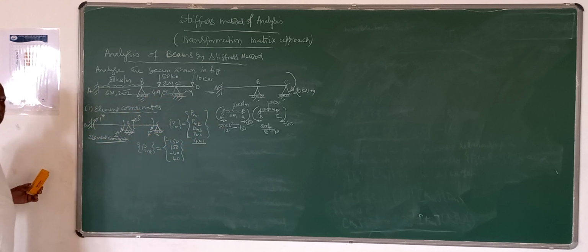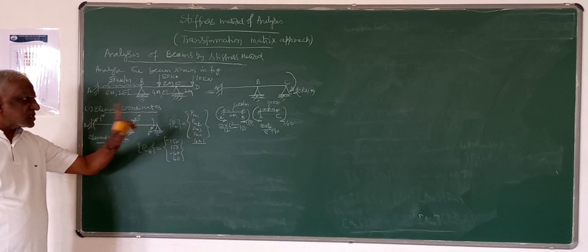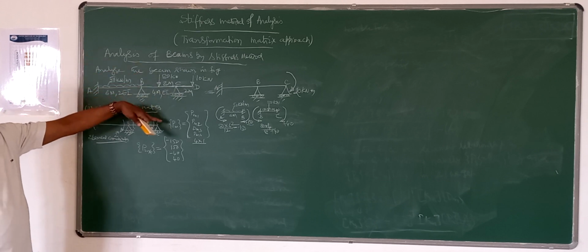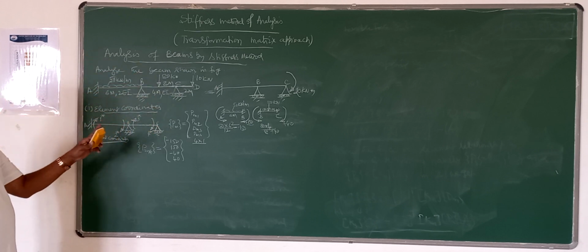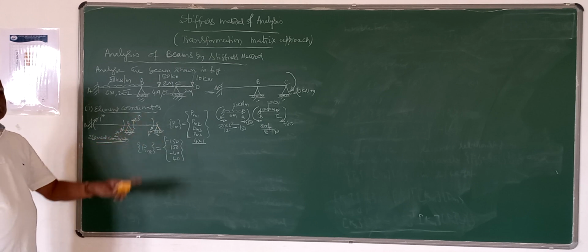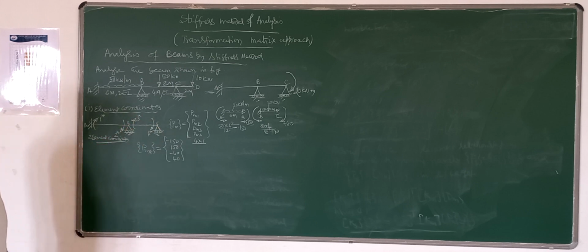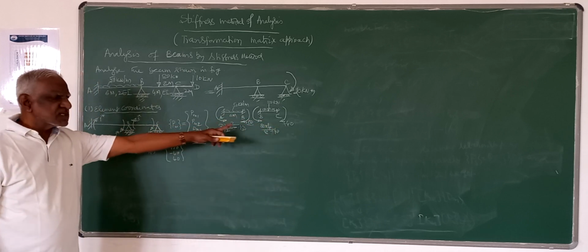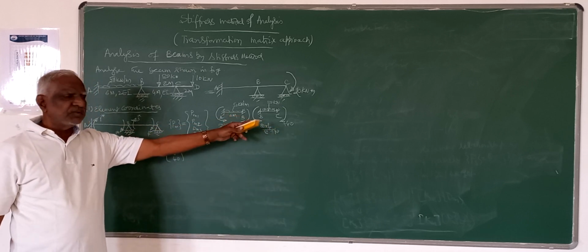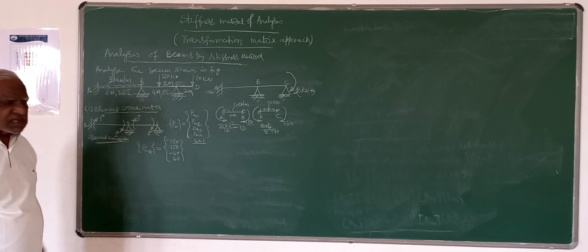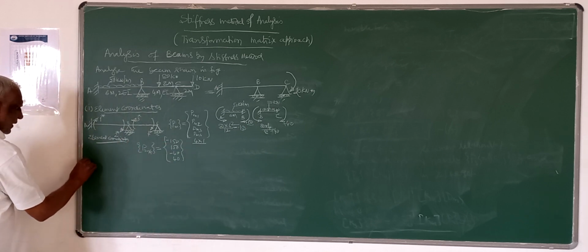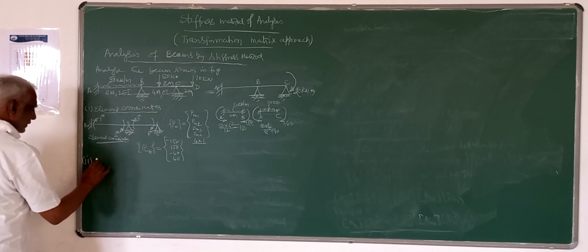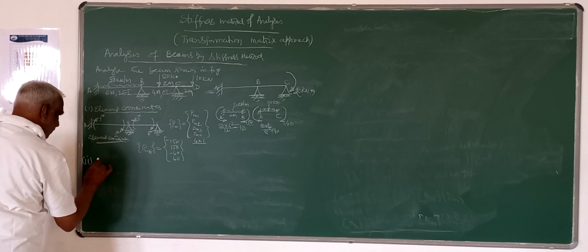Ultimately at the end we have to determine these forces, and to determine these forces, first, whatever external load is there, I have to replace it corresponding to these end element coordinate loads by finding their fixed end actions in this fashion. This you already know, the standard fixed end moments that you have to replace it. That's the first step for element coordinates. Then the second step is the system coordinates.